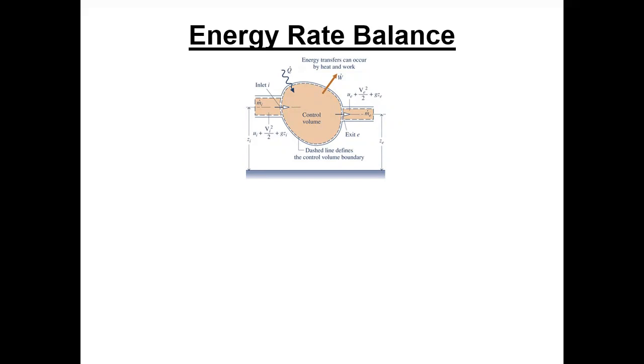We can have heat transfer. You've got a Q dot term up there. That one Q dot term represents the net heat transfer all around that control surface. So it could be coming in on the top, it could be going out on the bottom. Basically you have to sum up all of the heat transfer effects, and they show the arrows in the positive coordinate direction.